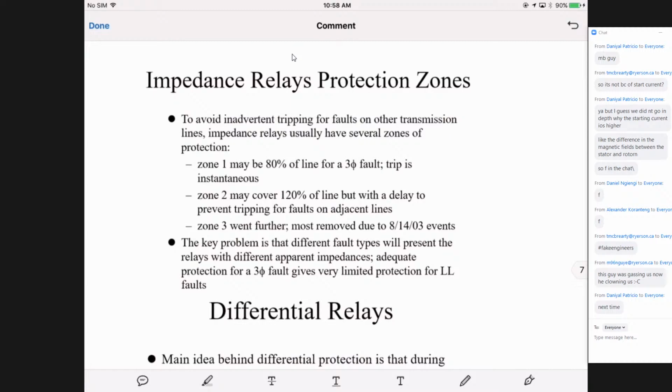And you learn the symmetrical components. Usually we would start with a three-phase fault, but it can give very limited protection for phase-to-phase faults, not phase-to-phase-to-ground, just phase-to-phase, when the two cables, in a high wind, swing. Usually this will not happen in a new design, because even if they swing, they will not touch each other.